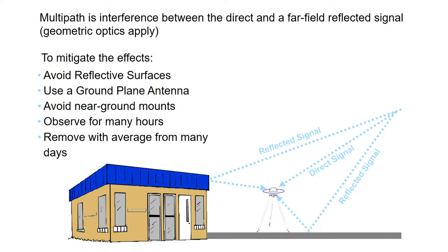But there is a limitation of this masking. Sometimes when signal availability is less, there are only 5 or 6 satellites available in your area. When you give more masking, like 10-degree elevation angle, you receive very few satellites in your data, which you don't want. If you are not able to receive more satellite data, you cannot constrain your solution or your parameters. If you want a fixed, accurate and precise solution, you need a larger number of satellites in your data.